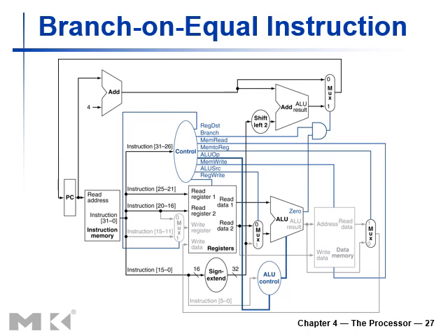So if you see the format of the instruction, that is BNE, branch not equal, dollar sign V1, comma, dollar sign V2, and a label. Branch not equal is also a conditional instruction, and it works in the same way, but now the condition that is tested is the not equality condition. Now what would be the possible values of the program counter, because we are reacting in the opposite way as compared to the branch equal instruction.